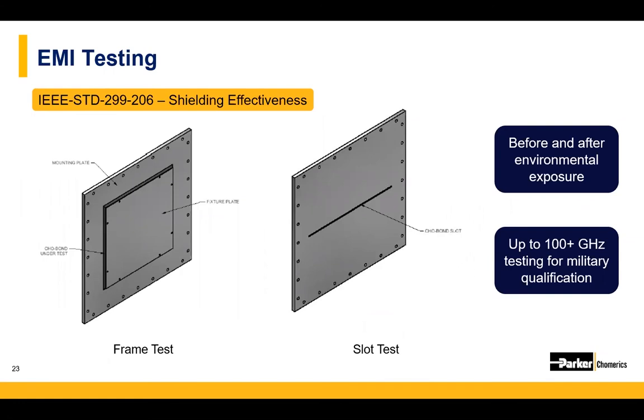So this is actually the standard IEEE shielding effectiveness test, where the conductive compound is dispensed on a metal plate in between two shielded rooms. So Chomerics does have test facilities, and we have a number of shielded rooms where we perform not only testing on our own materials, but also the overall systems and EMI testing for our customers' electronic systems.